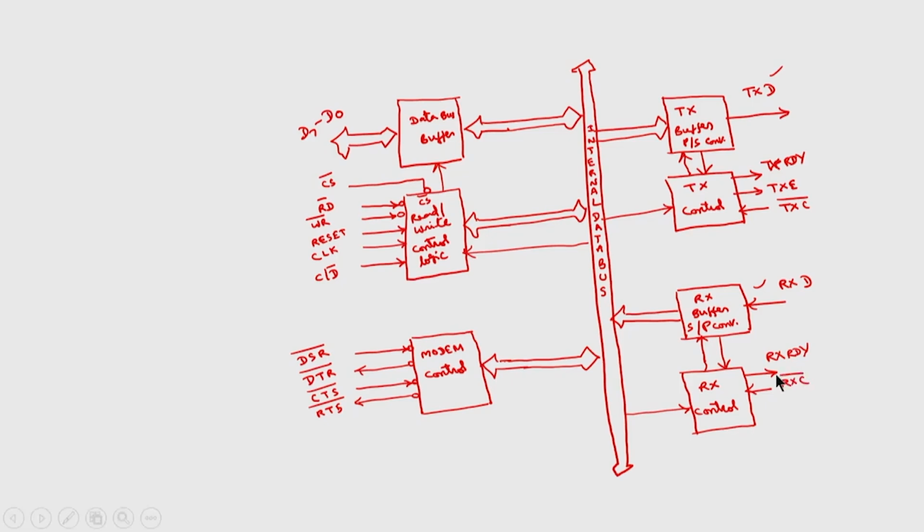Instead of transmitter empty, there is one signal called sync signal, which is the synchronous signal. So, these synchronous pulses are required in case of synchronous data transmission. Okay. This can also be called break character. So, these are the different signals of the 8251 architectural diagram.